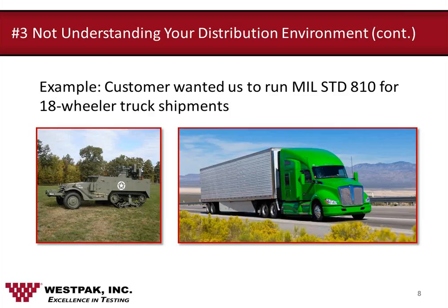Thanks, Tim and Chris. That is a good question. Yes, during flight shipment, a hole can be caused in a vacuum bag, and so what you can do is, part of the ASTM D4169 distribution cycle 13 is a vacuum test, so you expose it to the equivalent of 14,000 feet for an hour, and then it comes back and you run it through vibration, and so you can check to see if that vacuum bag is intact.